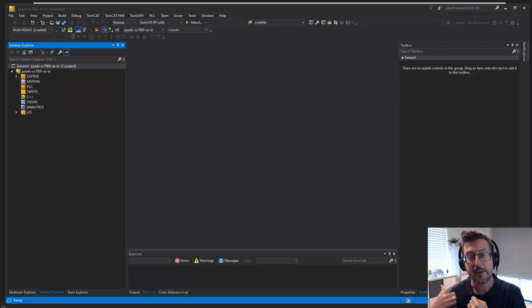They definitely can't do things which require DC clock, so the XFC terminals where you can get multiple values back, or support things like third-party devices. For that, you need a true controller that's going to run TwinCAT, configured in TwinCAT, that type of thing. The bus couplers tend to have their own web interface. You can pick what I/O is in there, but maybe you don't want to do that. Maybe you want something else. And so what I'm going to do is show you a possible solution.